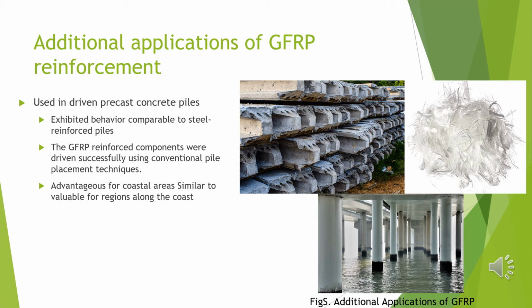Another application of GFRP shear reinforcement has been developed in driven precast concrete piles reinforced with GFRP bars and spirals. It was used successfully because it's possible to incorporate GFRP into the industry in these elements, and the structural behavior is good.